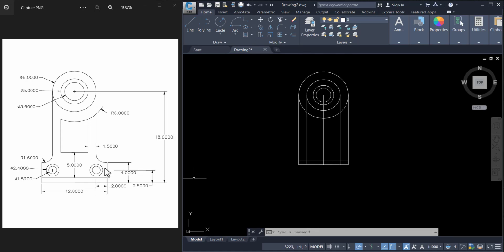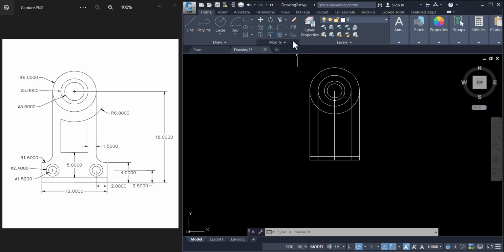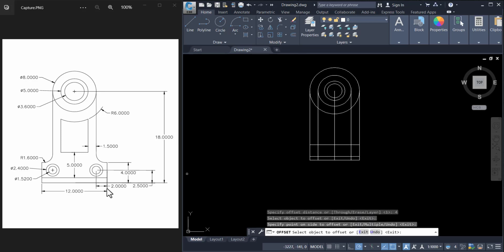The next one is I want to offset this particular point. You can see that there's a curve here. The offset here is about 4 meters. You can see it here. So I'll click the offset tool again, click 4 meters, and offset it to 4. The center point of this is 2.5. You can see it here. From this circle is 2.5.